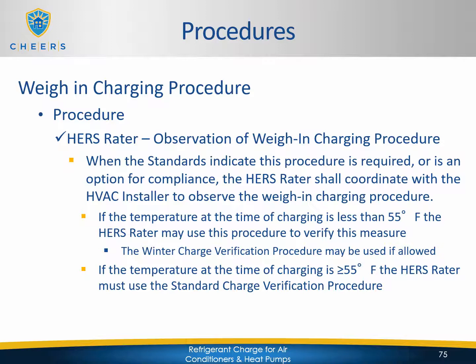You can do this if the temperature at the time of charging is less than 55 degrees Fahrenheit. The other option in those lower temperatures is possibly the winter charge verification procedure. Again, this is only applicable to equipment that is approved for that winter charge. If it's not approved for that, below 55, your only option is to observe the weigh-in.